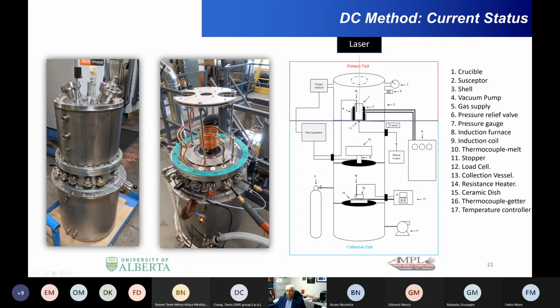This will be an improvement because by having the height, when you start the experiment with a known weight of material in your crucible, once it's molten and at a known temperature, you measure its height with the laser, bang, right there, we know the density at that temperature. And so that becomes an input into the model. And then the load cell information afterwards gets used to calculate the surface tension and the viscosity. So again, we're still using the same device and getting 3 properties.